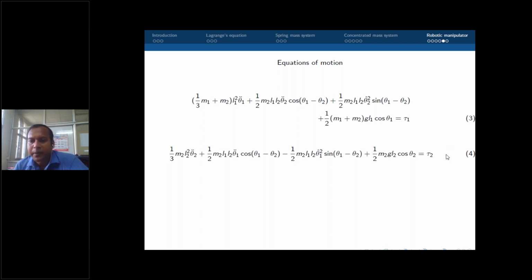You need to take care. See, if there is a prismatic pair, a prismatic actuator, then what is happening there? There is one mass and another mass is sliding through it, so it has another degree of freedom. I have taken two revolute joints, so you have to add another prismatic joint with it. Right. Correct. Okay. Thank you, sir. Any other question, please?